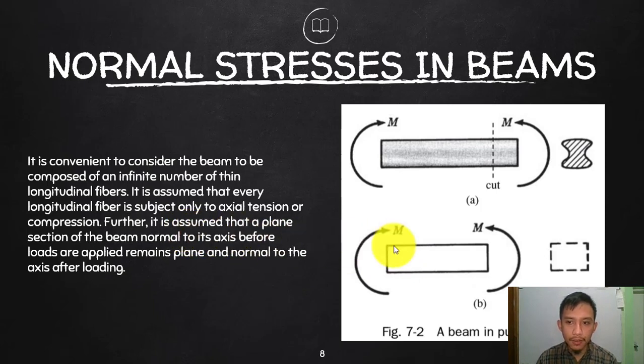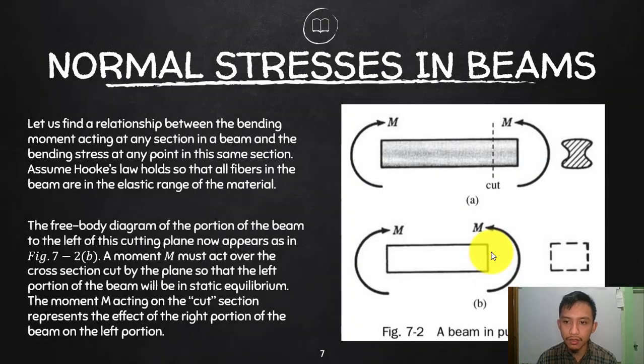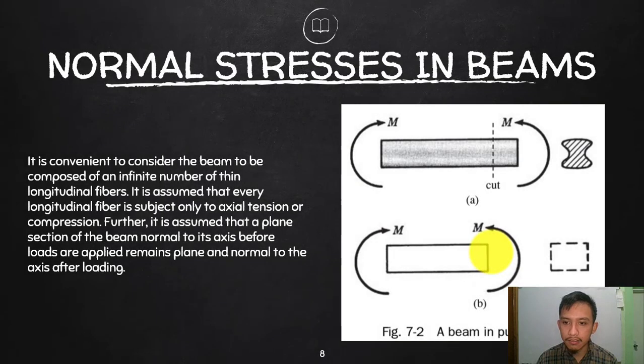And then of course, to relate that with the fibers that we are talking about, as I've already discussed a while ago, the beam, which is under flexural bending or bending, will undergo bending stress, which is composed of tension and compression. So each of those fibers there will undergo different intensities of stress. It could be compression or tension, and the compression and tension will be divided by that boundary, which is what we call the neutral axis or the neutral surface.